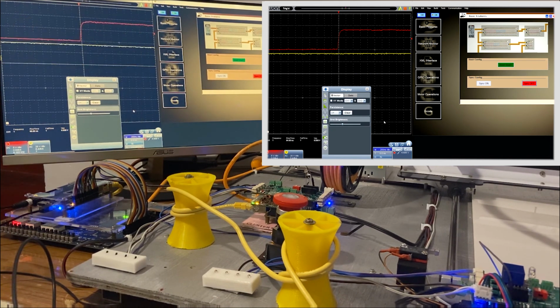The reason for this is that when synchronization mode is on, the master periodically sends its clock to the slave devices, and the slave devices adjust their time according to it and compensate for their internal clock errors. Here we have achieved roughly 50 nanosecond precision among 3 slaves.